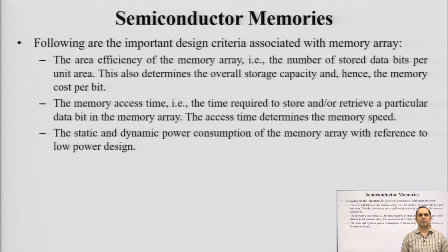well known performance parameter. Next is how the data is being stored or fetched, the mechanism of it, especially the storage mechanism, decides what type of memory we are dealing with. You can store the data in a static way, you can store the data in a dynamic way. Okay. This is slightly similar to the static and dynamic sequential circuits which we have also studied, right. If you remember, most of the dynamic version of circuits used some kind of a capacitor for charge storage.